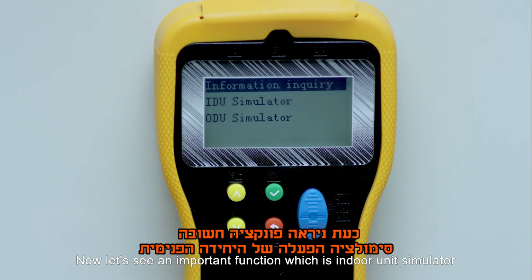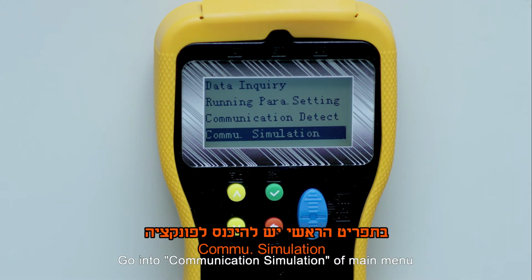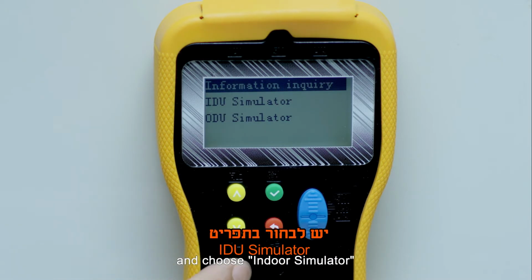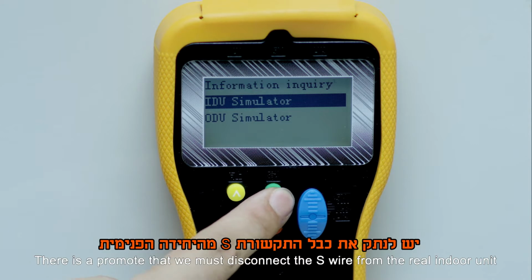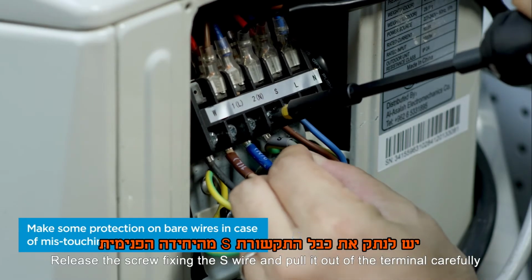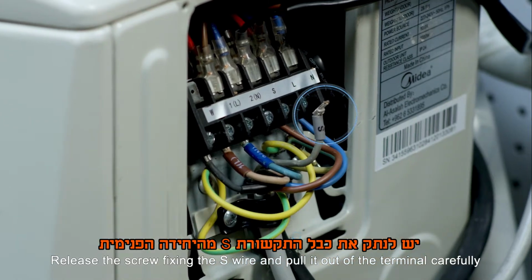Now, let's see the important function, which is Indoor Unit Simulator. The device will work as an indoor unit to start the outdoor unit directly with the function. Go into Communication Simulation of main menu and choose Indoor Simulator. There is a prompt that we must disconnect the S-wire from the real indoor unit. Release the screw fixing the S-wire and pull it out of the terminal carefully.